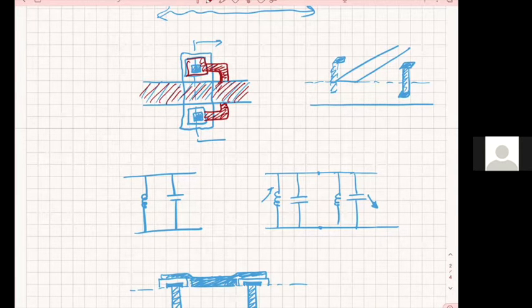However, for the other ones that you can realize using transmission lines, do them, because as you can see, doing lumped elements requires more fabrication steps, and at the end is more difficult and more expensive. So nobody wants to go to unreasonably complex fabrication steps for something you can do using a transmission line, all right? Did this cover your questions? I would say so.